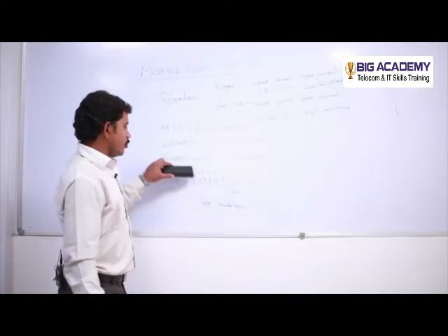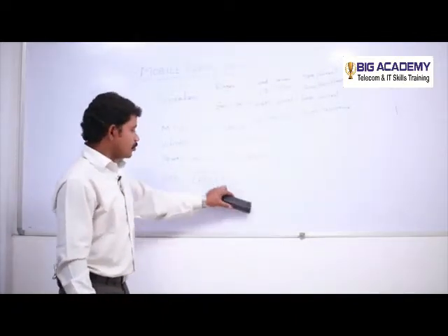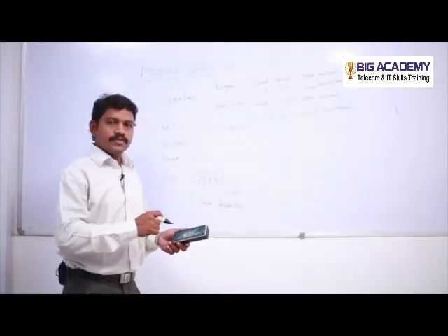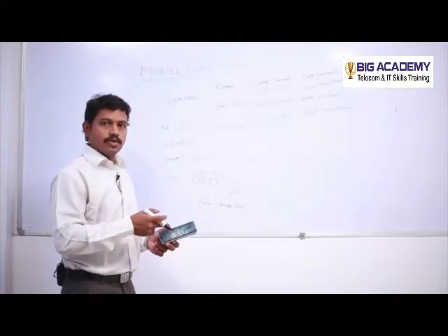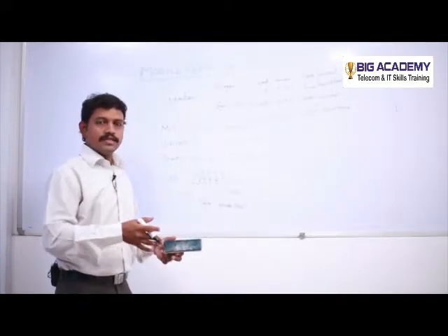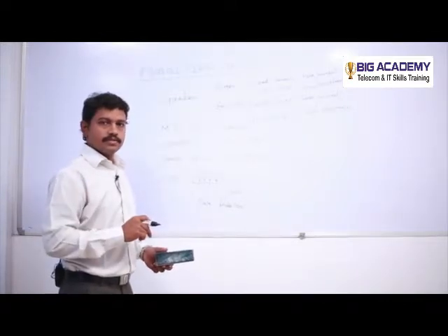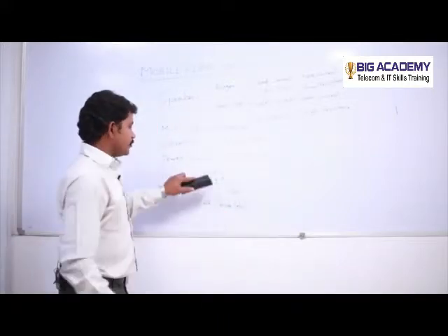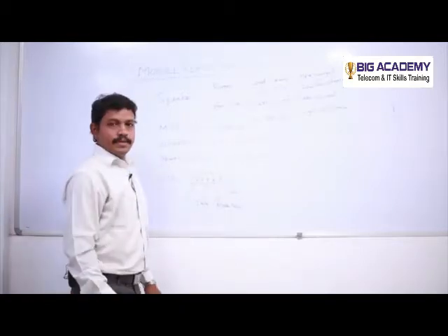What is mode select? We know all these voltage, data transfer and common ground. And what is mode select? Whenever you connect your mobile phone with any interface device to the system or laptop, it shows some options, whether you are going to charge, whether you are going to transfer the data or you are going to debug. So that is the mode. Whatever you want, you can do the selection. So that thing will be transferred with the help of pin number 4. So this is the USB pin connector.